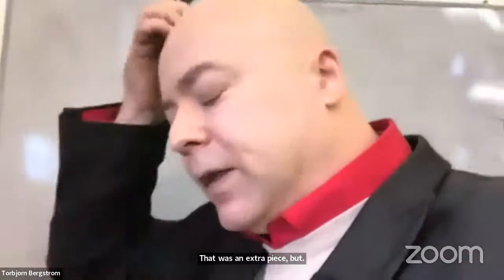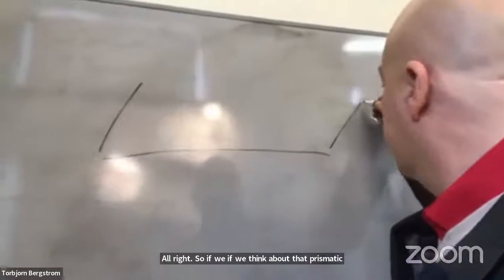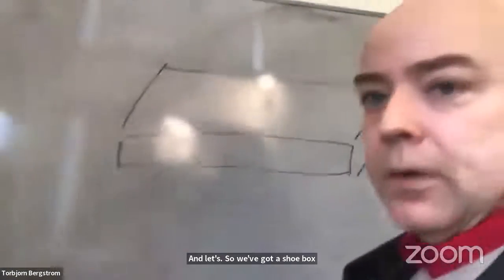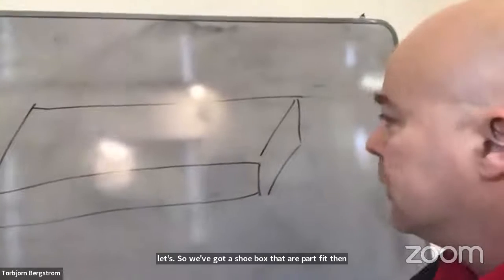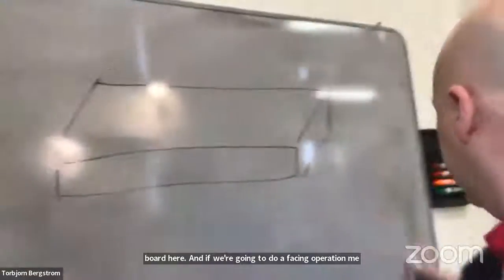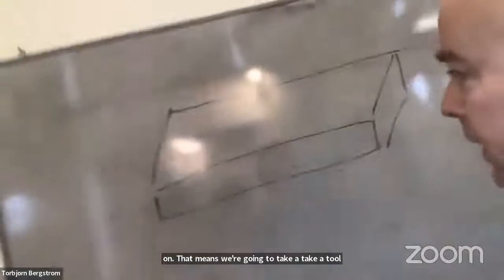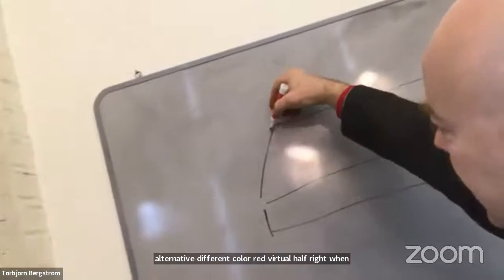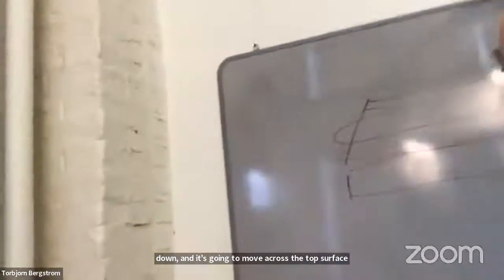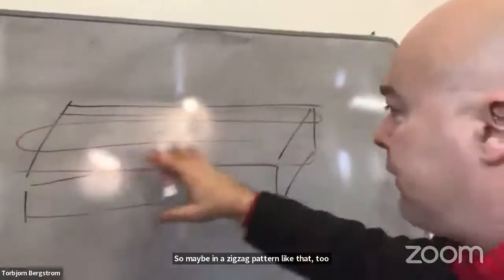Right, so if we think about that prismatic material, we've got a shoebox that our part fits in. I've drawn a representation of the shoebox on the board here. If we were going to do a facing operation, that means we're going to take a tool. I'll try a different color. Red for our tool path, right? We're going to take a tool that's going to come down and move across the top surface here, maybe in a zigzag pattern like that, to remove just a layer of material off that top surface.